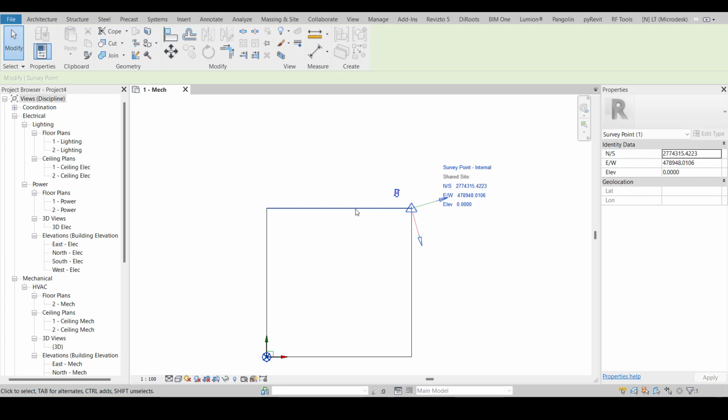So what you will do, suppose it's a stadium, and you were standing somewhere here, and there is some manhole to be made there, or any gutter you are making, or for example a fire hydrant, whatever. So you went there physically and marked that by GPS, by your mobile phone, in the worst case I'm saying, okay. Less precise, but still it can give you the point. Now that point you can convert into this project coordinate system.